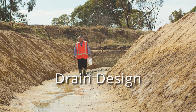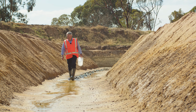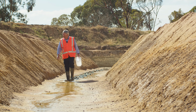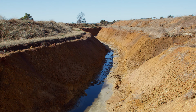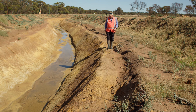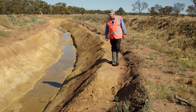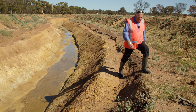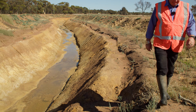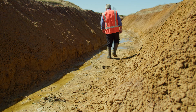One of the critical aspects in drain design is the shape of the drain. In other words, what is the slope of the side batters? What is the width of the drain floor? And how deep is that drain? When it comes to the side slopes, they can vary considerably depending on your soil types. Some soil types are much stronger and more stable, so your sides can be more vertical.